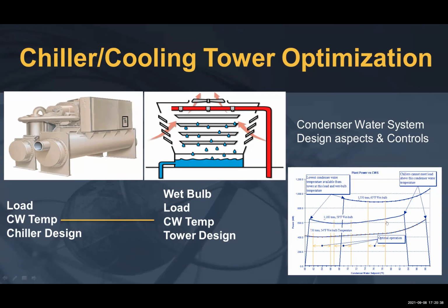Now, a good amount of research has happened showing there is a common temperature at which, both put together, the energy can be optimized. And that's what we are talking about, the optimum condenser water temperature, because the curve goes down and then at an optimal temperature, the combined energy of chiller and tower goes up. Now that is where the control system has to capture that condenser water temperature, which is the optimum at which the system can be designed to ensure the peak performance of the combined load.